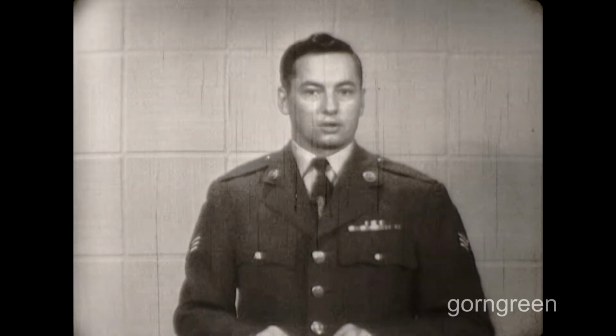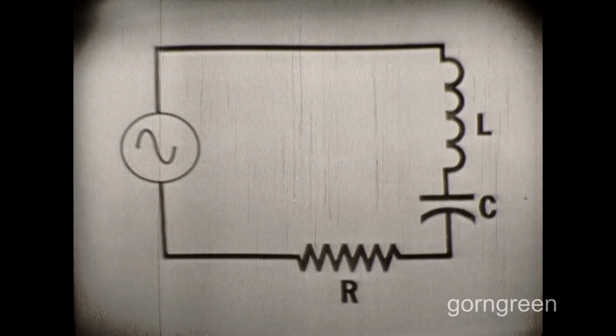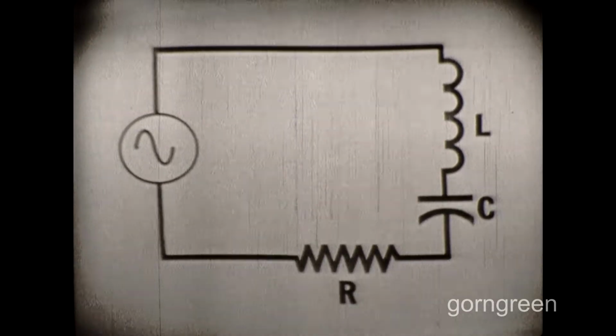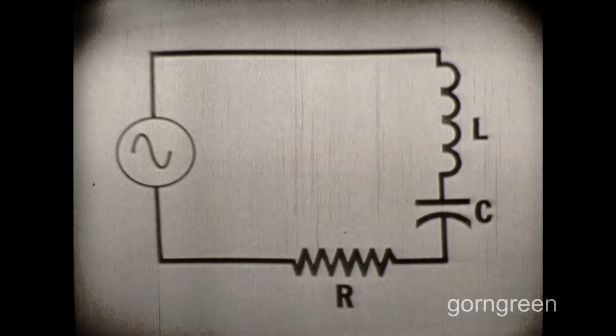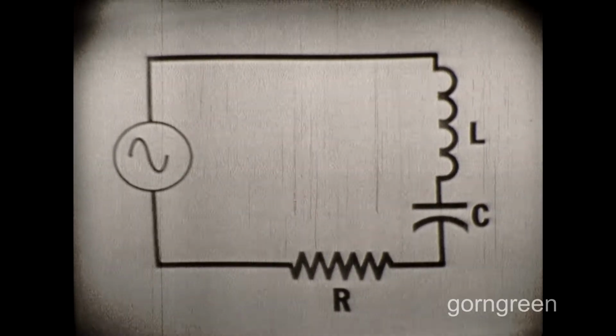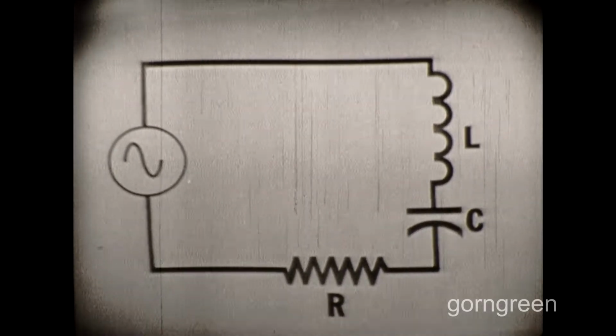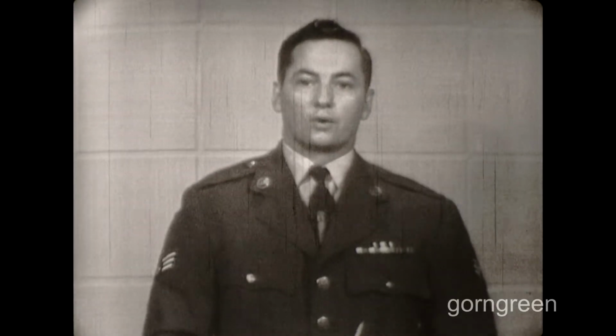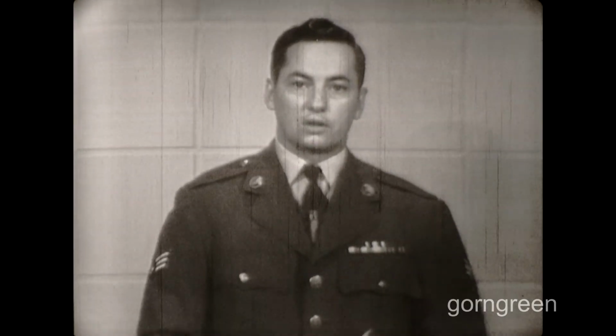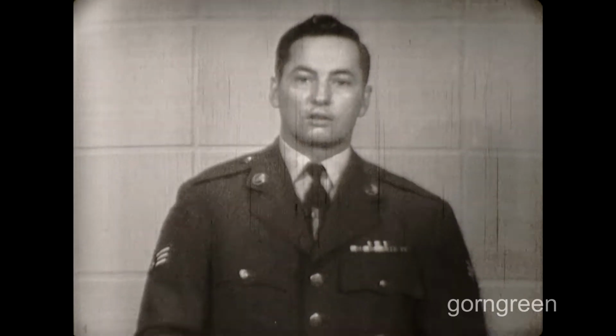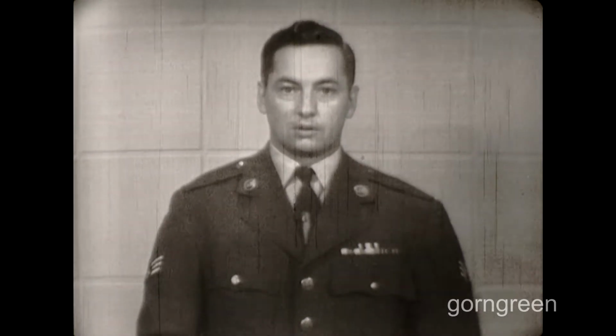Well, now that we have formed the basic antenna, let's see what it looks like electrically to the power source. Since it is actually a split open-end quarter-wave transmission line, it will exhibit the same electrical properties. In other words, it will appear to the power source as a series LCR circuit. Now, if the antenna is cut to serve one frequency, it will be physically and electrically 1/2 wavelength for that frequency. However, if it is to serve a variety of frequencies, it must be varied in electrical length to be 1/2 wavelength for all those frequencies.